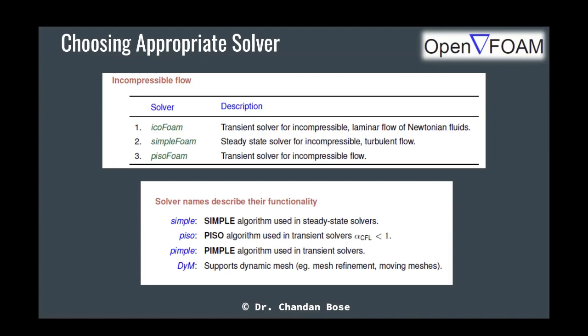Right, so in case you use, which we will be discussing in the next session, fluid structure interaction or moving mesh problems, you will have to use the dynamic mesh motion strategy. And for that, you need to include that additional dictionary file, which is called dynamicMeshDict.